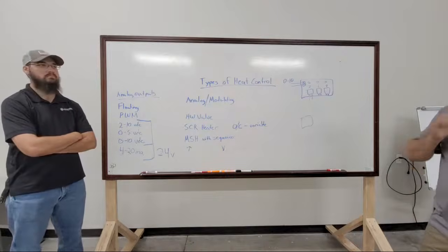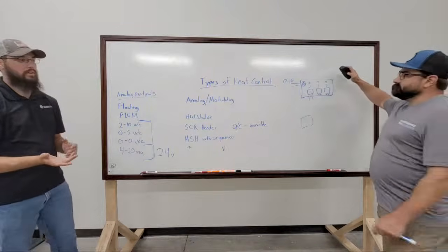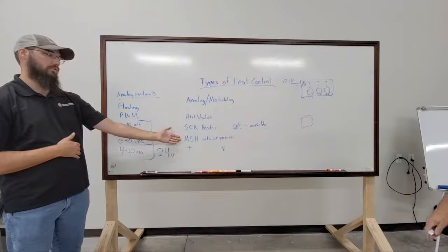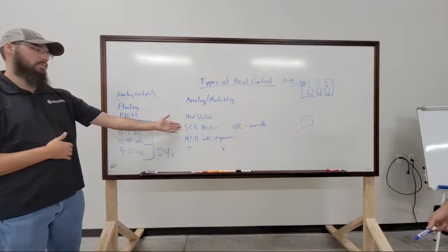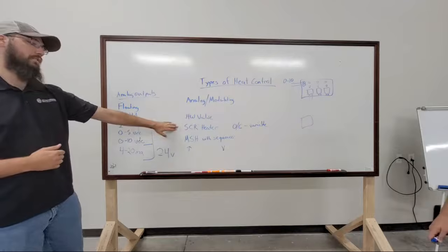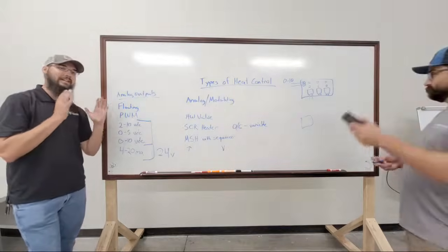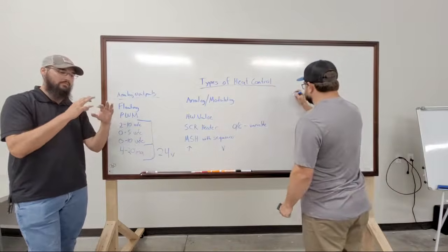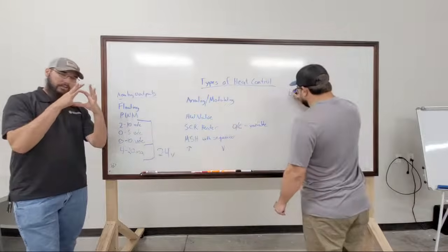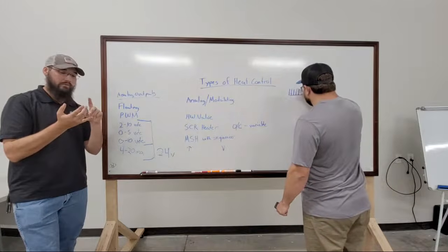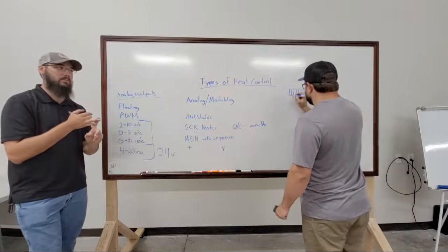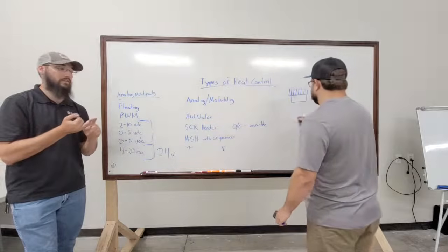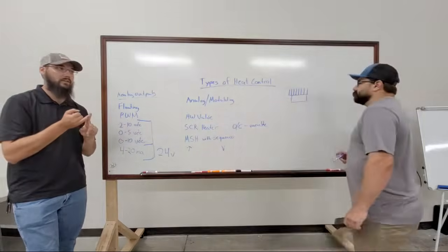Yeah. One of the main ways to know what you have, so I think it's pretty straightforward if you have a hot water valve versus electric heat. Yeah. The biggest way to know without even opening a panel if you have SCR is they'll have a large heat sink attached to the back of that module. So the SCR, like I said, it's a solid state device. Usually it's a square about yay big, and there is a difference between a single phase and a 3-phase SCR module. So you have to be careful if you're ever replacing them which one you have and which one you get, and they're very expensive. We're talking like $1,000 expensive.